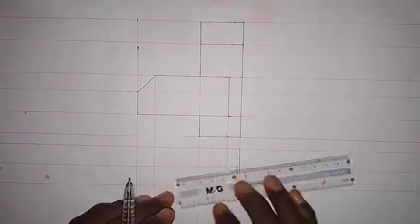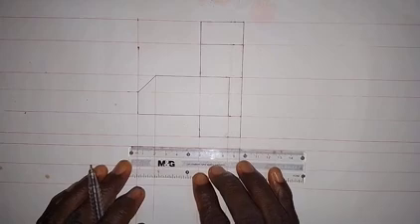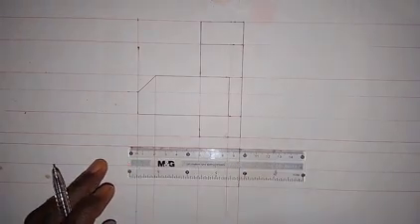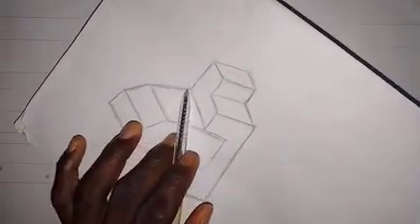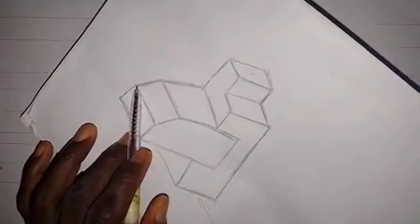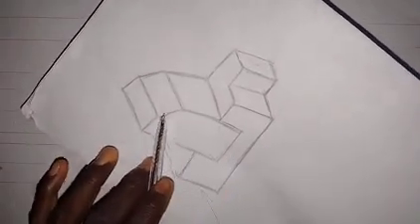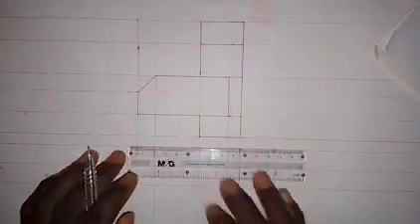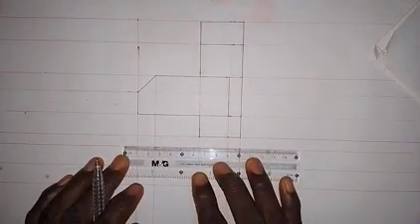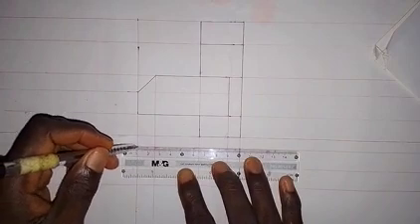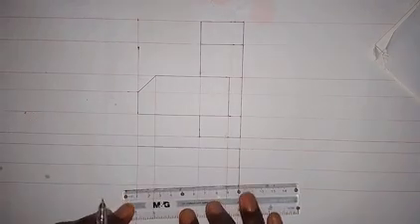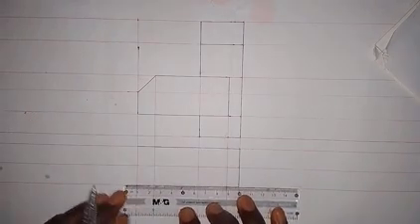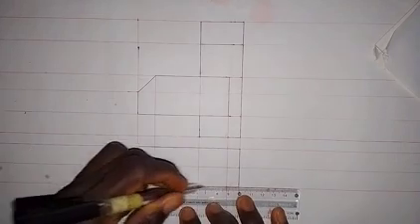For the rectangle that we have here, looking at the assembly that we did, we are going to have this line merged with this and merged with this one. The same applies to this, so the lines will be merged together. So for this line I need to make it a thick line all through, and I also need to make this one a thick line all through.